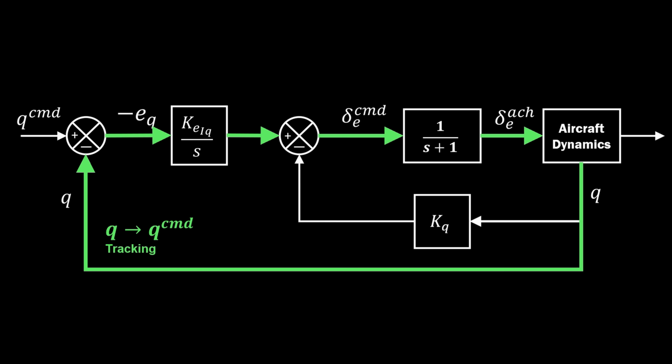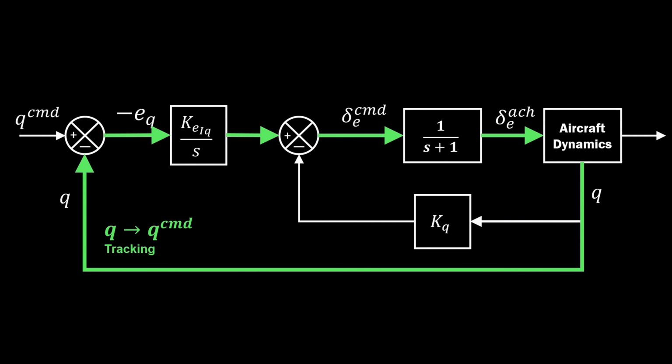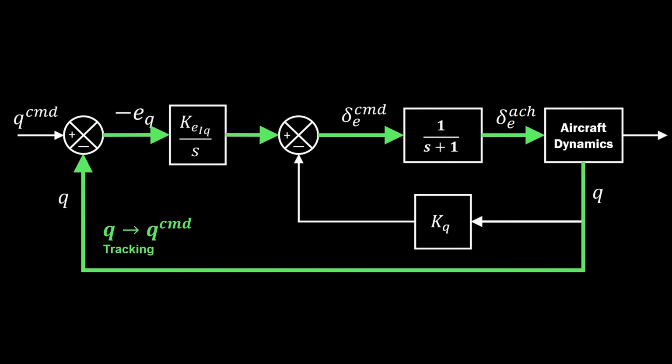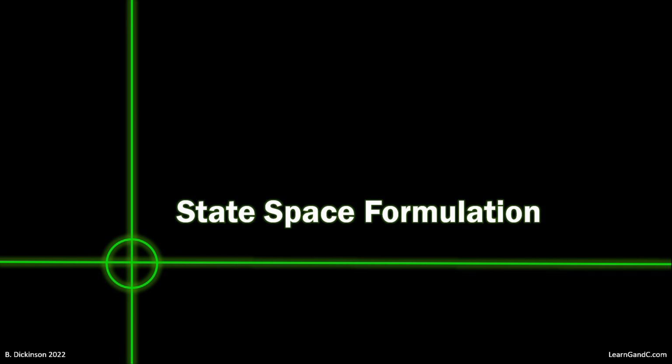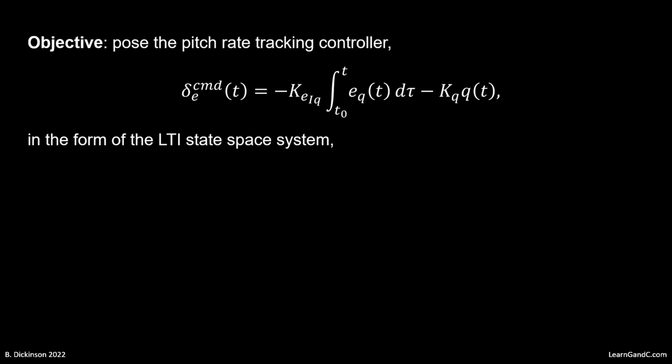To proceed with analysis and tuning of this controller, we're going to work with both frequency and time domain models, and being able to fluently work in both domains is a very powerful skill set. We're going to implement the pitch rate tracker with a nonlinear aircraft simulation. So the controller represented in the time domain is going to be very convenient. As a linear model, we can write the controller in a linear time invariant form.